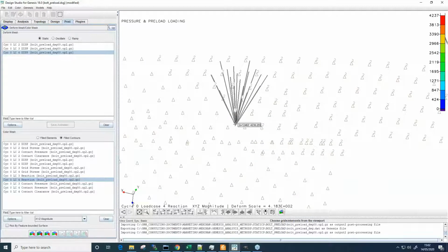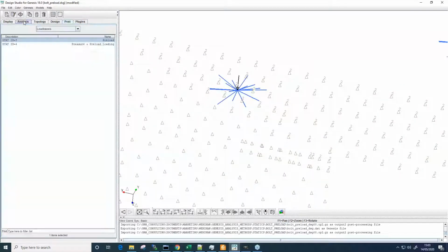So this is the bolt control grid. If you notice here, we've got a load of 4,236, and that's the tensile force in the bolt once we have a 5 kilonewton preload applied, and then the pressure applied as well. So I will need to do one more run to demonstrate it a bit more clearly. I would skip through it, but I think it's important.